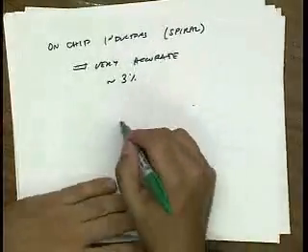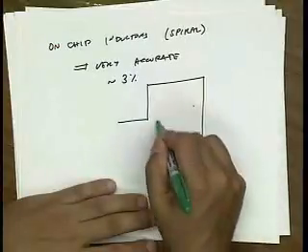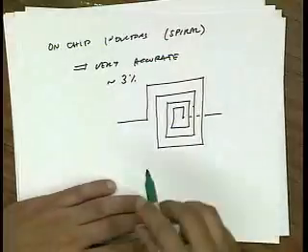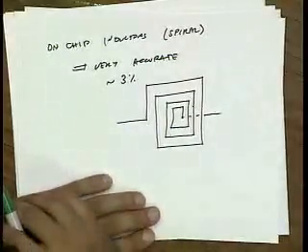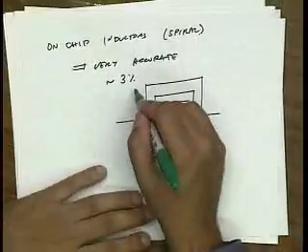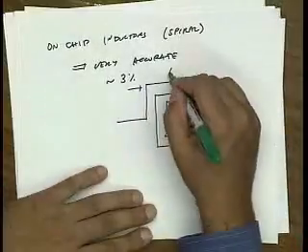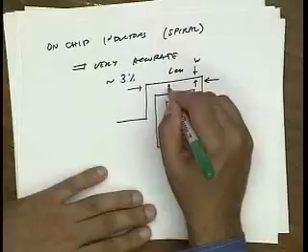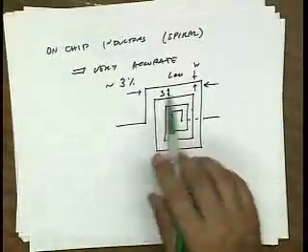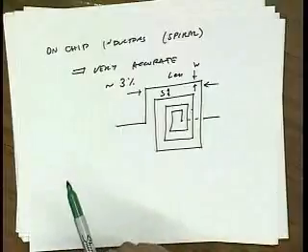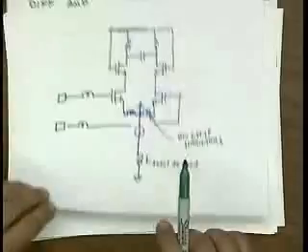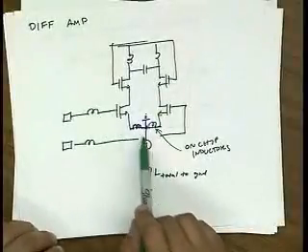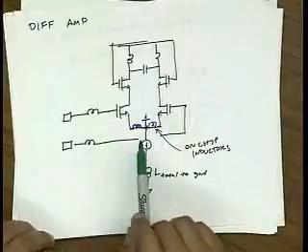And that's because the way we build these inductors is we build either square spirals or polygon spirals. It has to be a planar structure, so we have to make it in a plane. But the inductance is more or less a function of this dimension, right? Let's say the length, the width of the conductors, the spacing of the conductors. And these are very well controlled in an integrated circuit process. And that's why the inductance value is so accurate. So I can synthesize a very accurate degeneration inductance here and synthesize a very accurate real component of the input impedance with a differential topology.